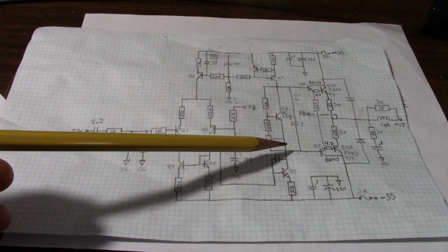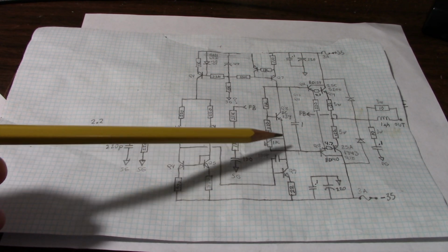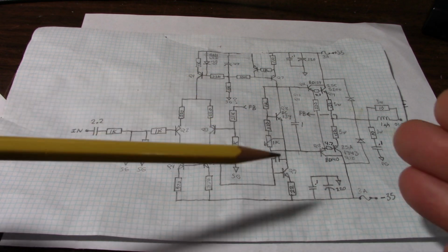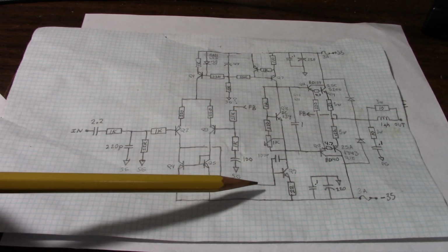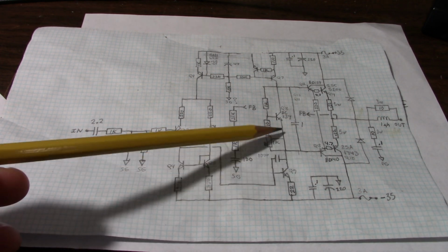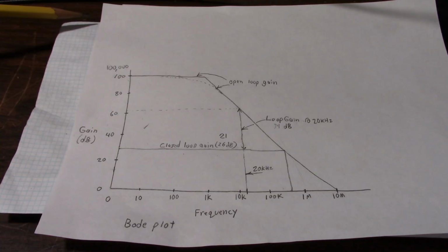And because of its position across the collector and base of the transistor, it has some negative feedback effects. And it does something called pole splitting, where it brings the pole frequency on the input down and increases the pole frequency on the output of the circuit. And that pole splitting effect works very good for frequency compensation.